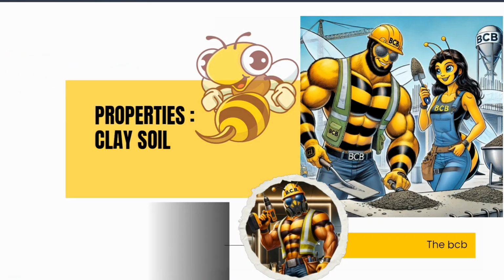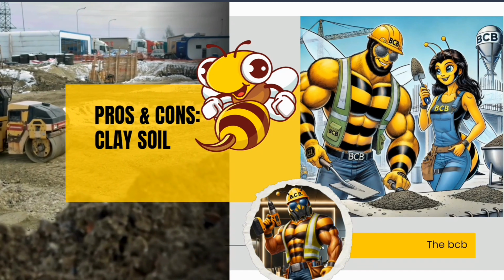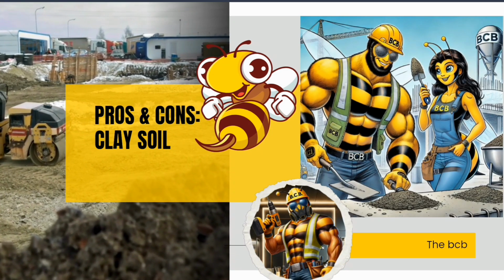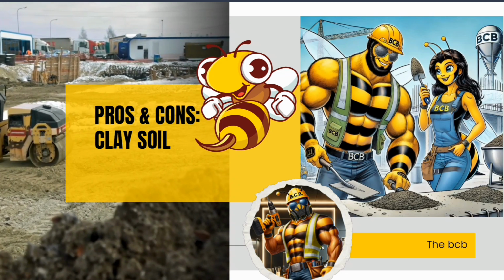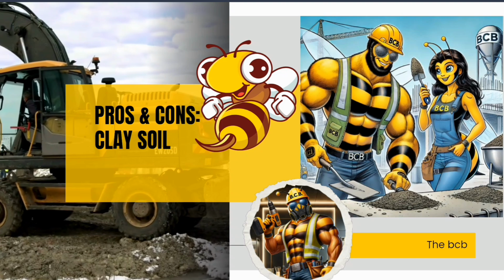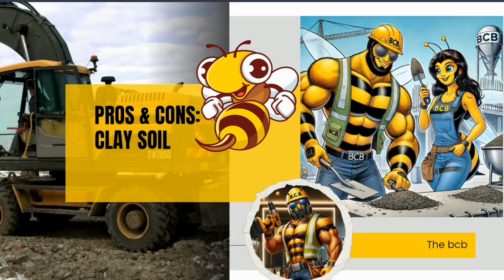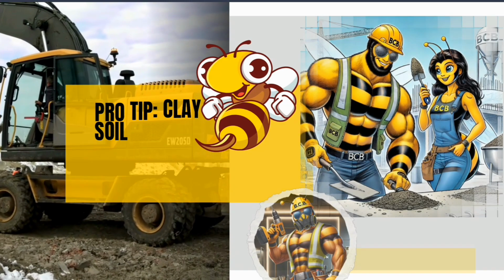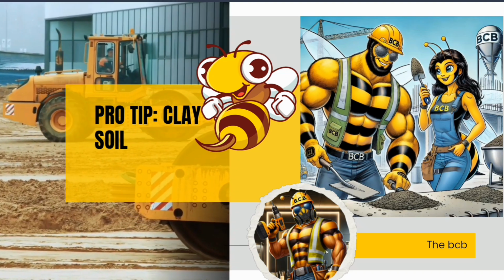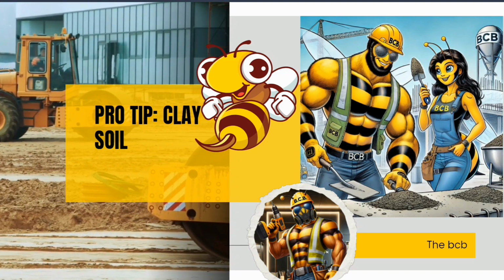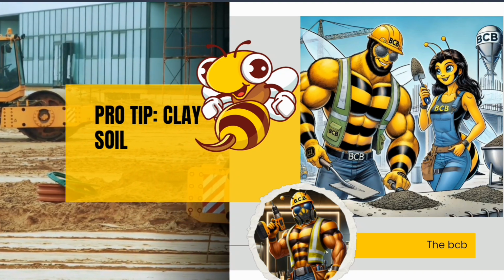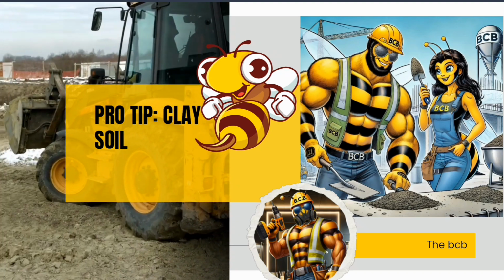As the soil expands and contracts, it can lead to cracks and even differential settlement in the foundation. Now, the pros of clay soil: it's highly cohesive, which can provide stability once compacted. However, the cons far outweigh the benefits for most construction sites. The expansive nature of clay soils can lead to long-term issues if not properly mitigated. To counteract the expansion and contraction of clay soil, it's critical to use deep foundations like piles or caissons that bypass the unstable upper layers of soil. You can also implement proper drainage systems to reduce water retention around the foundation.